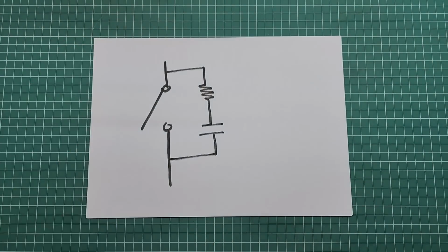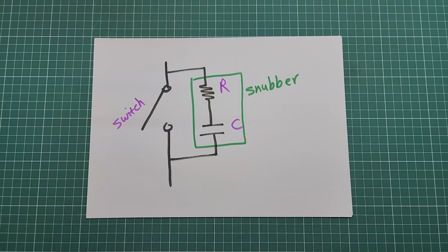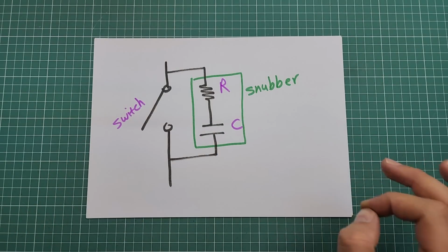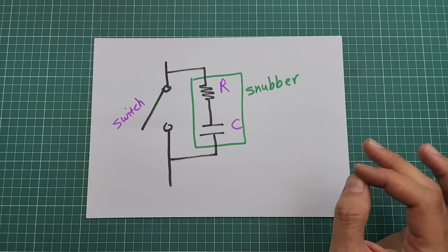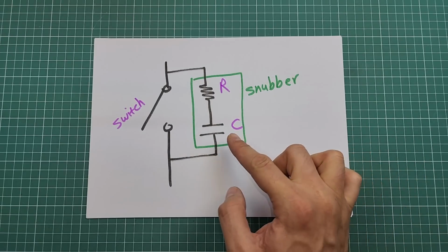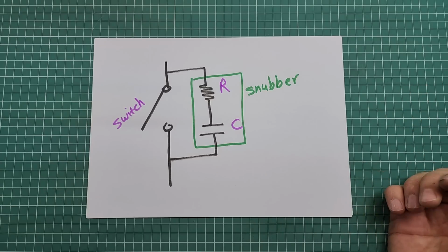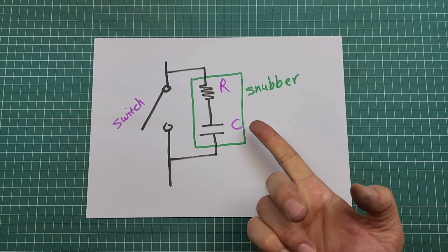Anyway, I said that polyester capacitors are stable, have a high voltage rating, and have a high frequency response, right? A high voltage rating along with high frequency response and stability makes plastic film capacitors suitable for snubber circuits. A snubber circuit protects switches like semiconductor devices or loads from voltage spikes during the switching process. It typically consists of a resistor and a capacitor to absorb or dissipate transient energy, enhancing device reliability in power electronic applications.